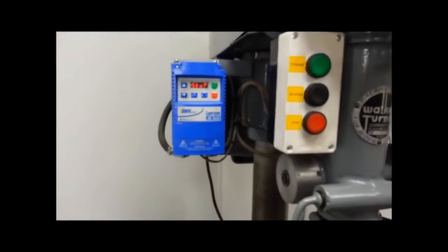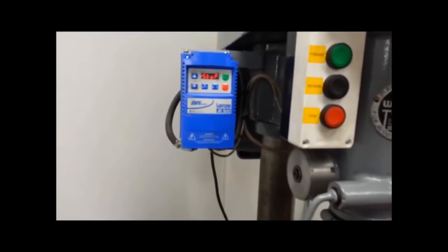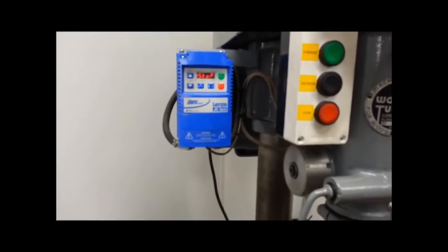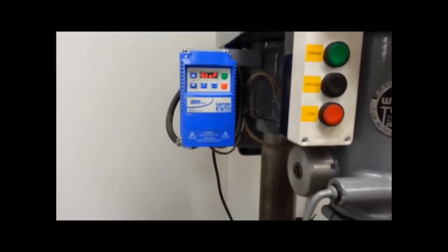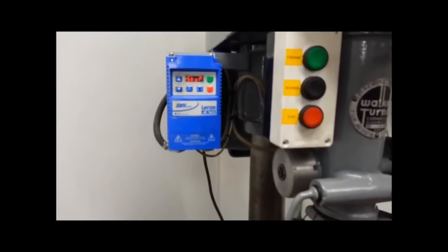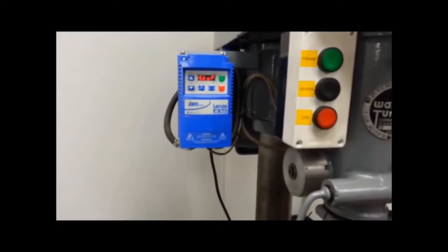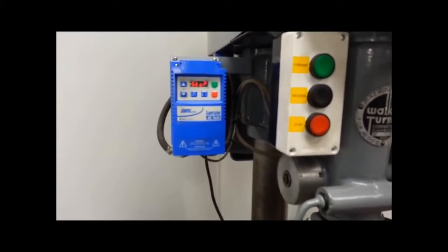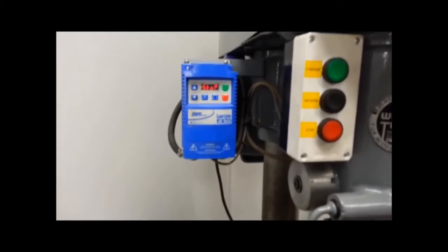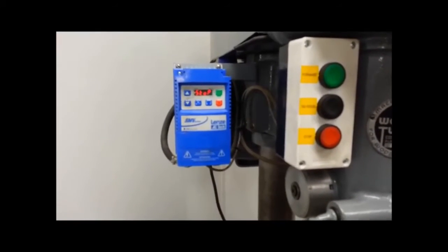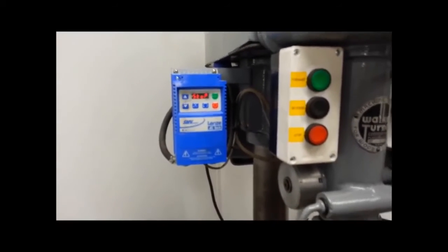There are 2 types of drives, and 2 ways drives can be programmed. One is called a variable torque, and one is called a constant torque. Variable torque would be used for maybe a blower, because as the RPM increases, so does the load, as the fan is trying to move the air. But a constant torque would be something for maybe a conveyor, where it always has to move the same amount of weight no matter what. So you have to be aware that there's constant torque and variable torque.